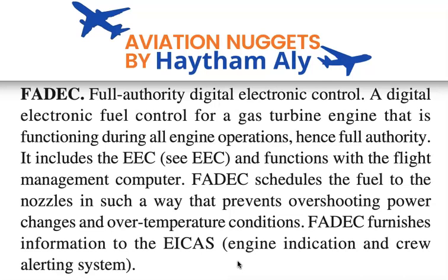Okay, everybody, I hope by these short minutes you got a good knowledge now, or refreshed your knowledge of what is meant by FADEC. As a summary, we will repeat what is meant by FADEC. FADEC is a full authority digital electronic control. It is a digital electronic fuel control for a gas turbine engine that is functioning during all engine operation, during starting and during transient operation. Hence it is a full authority. It includes the heart of the FADEC, which is the EEC, the electronic engine controller, and functions with the flight management computer.